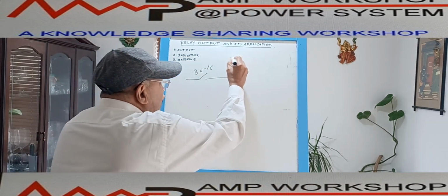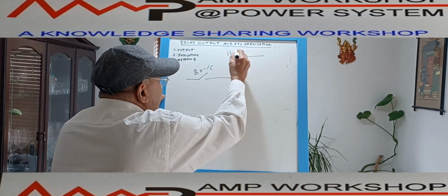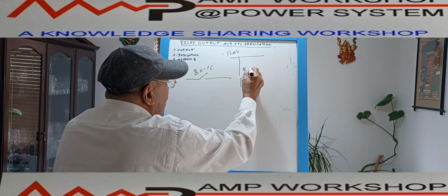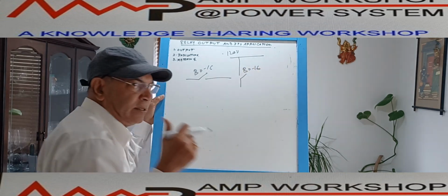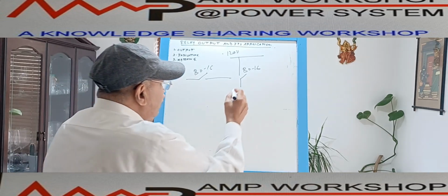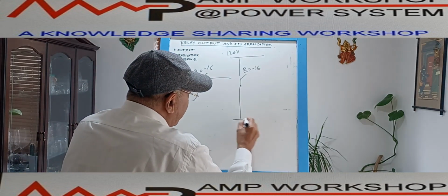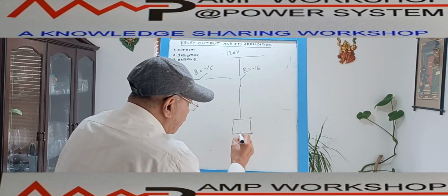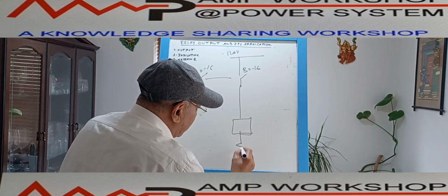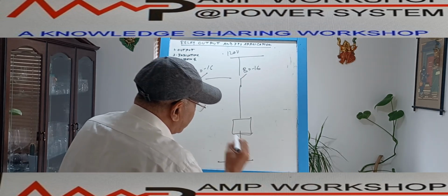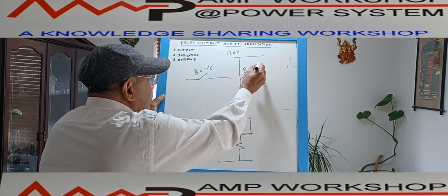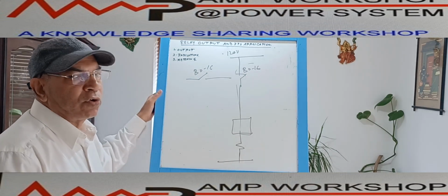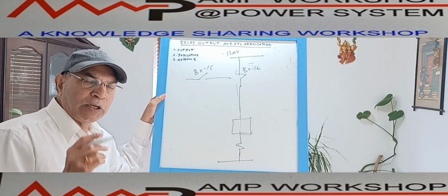Then what will happen? This is 120 volt DC positive. This is the B016 output contact of the relay, which is activated by the closing button on the relay. Then it will go through the various interlocks, the isolated interlock and all these things in the closing circuit. It will go to the breaker closing coil. This is the breaker closing coil. So when this turns on, immediately the breaker will close. So these binary outputs can also be assigned for the closing purpose.